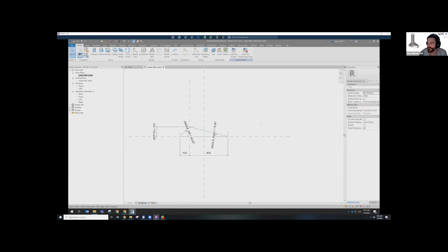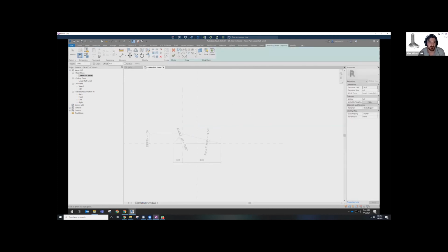It also allows the team to quickly iterate through designs. If you give someone an adaptive panel and ask them to update a profile, there's a way higher skill needed to complete that task than with a structural column. If you have a structural column, you don't even need it to be adaptive. You're just creating an extrusion at that point.